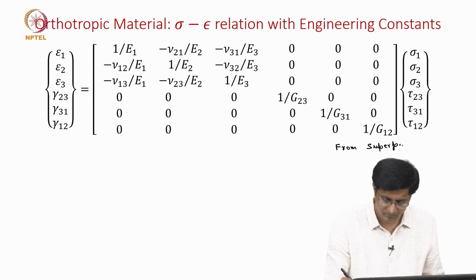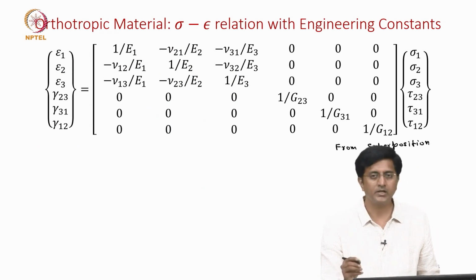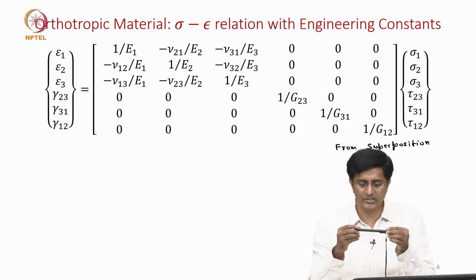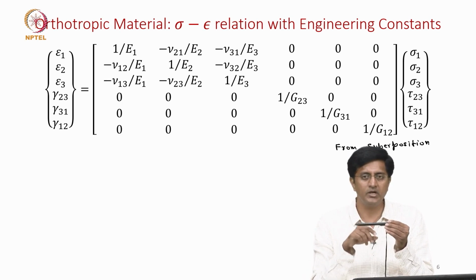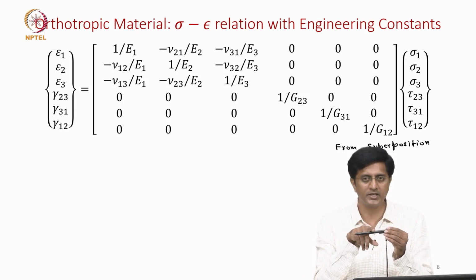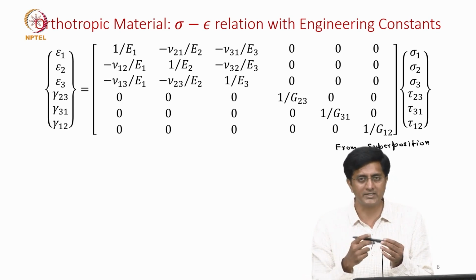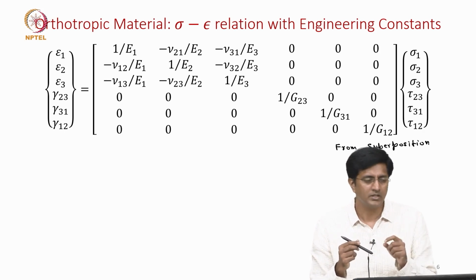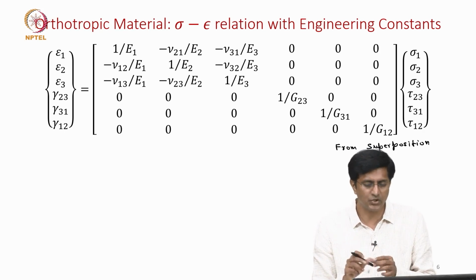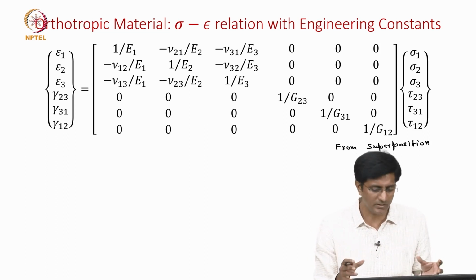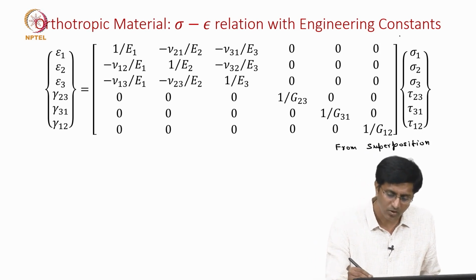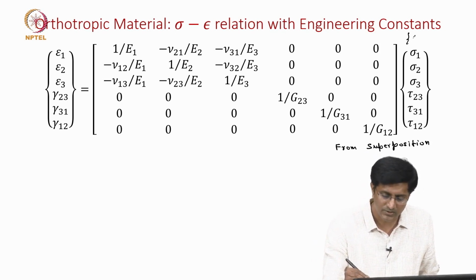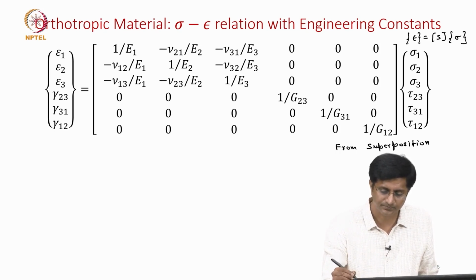meaning that in the first experiment, it is only uniaxial in direction 1. In the second experiment, it is uniaxial in direction 2. Similarly, I could have done another experiment uniaxial in direction 3, and the 3 different experiments we have done with one shear stress in each of the experiments. So, if we bring all those 6 experiments together and then we replace the compliance terms, now we get this compliance matrix, because we have said that strain is written as compliance matrix S times the stress.